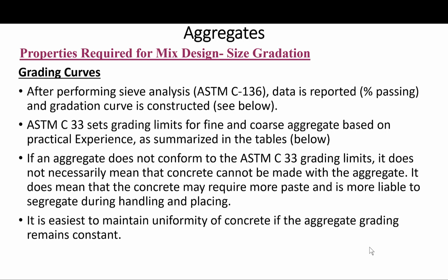If an aggregate does not conform to ASTM C33 grading limits, it does not necessarily mean that concrete cannot be made with these aggregates. It does mean that the concrete may require more paste, and maybe it will be more liable to aggregate segregation during handling and placing. That's what it means. So it is easiest to maintain uniformity of concrete if the aggregate grading remains constant.